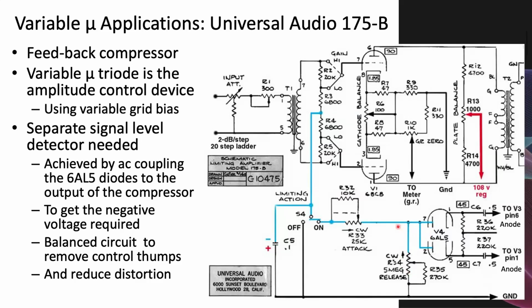You'll notice that having the separate rectifier allows you to control both the attack of the device and the release of the device, of the voltage stored on this, if you like, time constant capacitor. So again, fairly simple circuit, but nevertheless quite a powerful one.